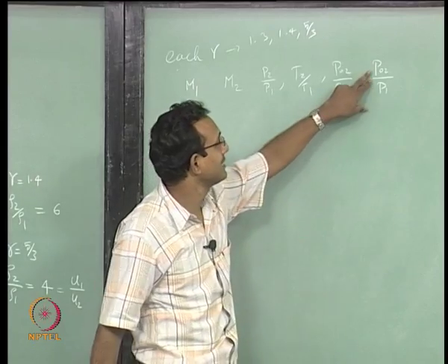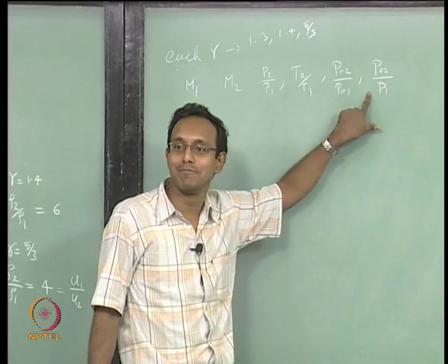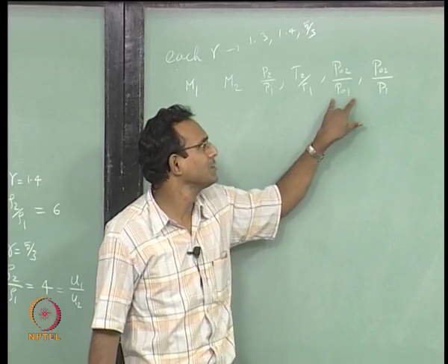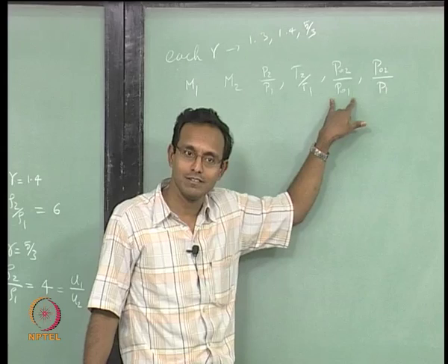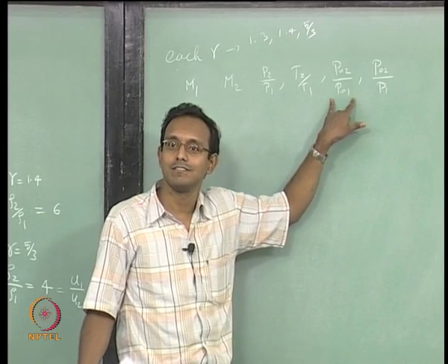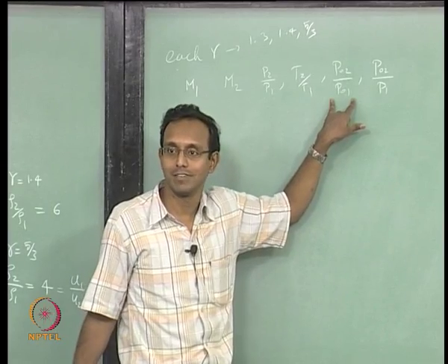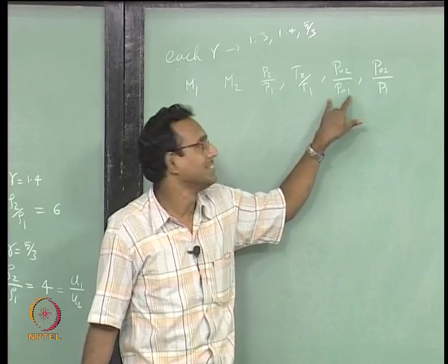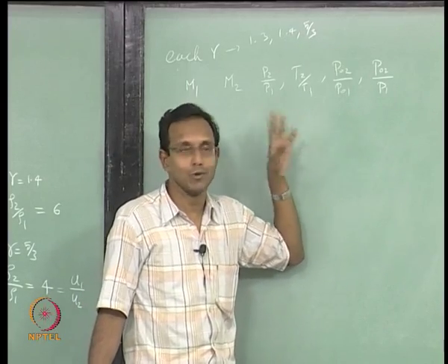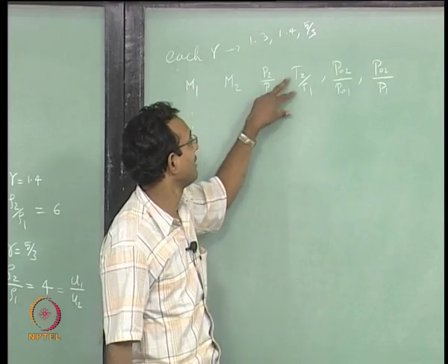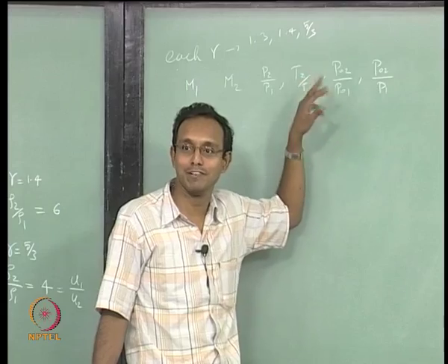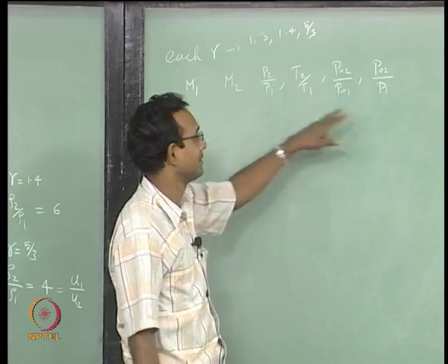And there is one special thing, p02 by p1, it will be very helpful in solving problems, we will see that. When will I use this p02 by p01? To find entropy jump. Delta S is minus log of this value. You have to of course know in your tables whether they are giving it as p02 by p01 or p01 by p02. Different books will give you different things. You have to know what is written there on the top.